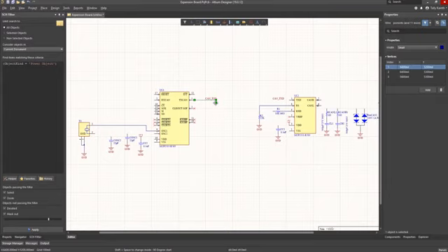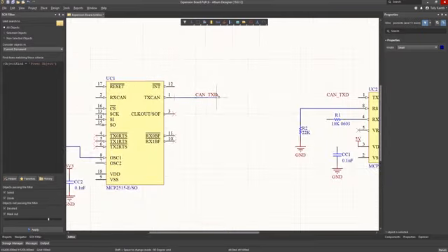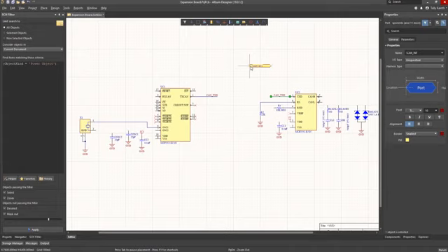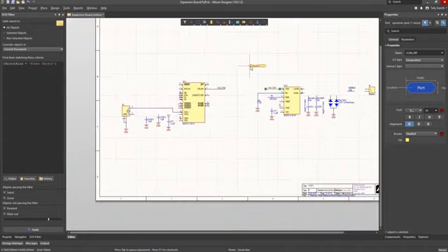Here we illustrate a connection using net labels instead of a continuous wire connection. In this case, CAN_TXD. These two wires are connected because they have the same net label and are on the same sheet. To connect pins on this schematic to the SBC/IO schematic, we will need to add a port. Click on the port icon on the active bar menu and then hit Tab to edit the name if needed. The name is used to provide the connections. These must match exactly. If needed before placing the port, we can rotate it using the space bar.